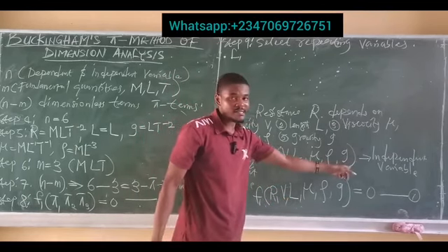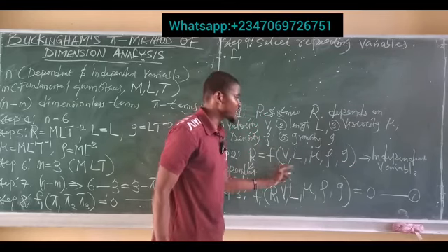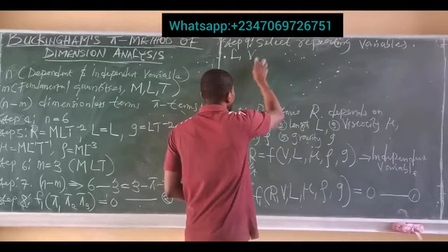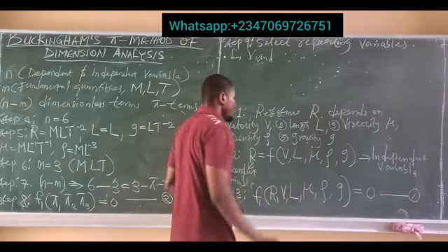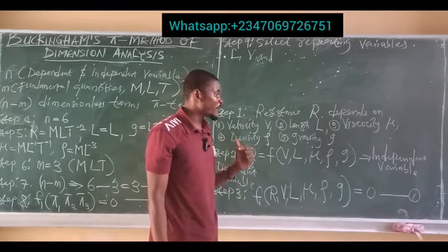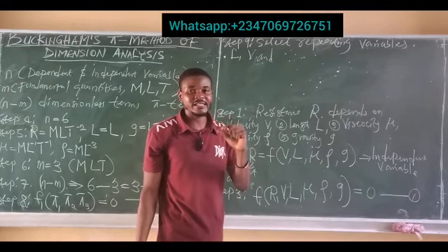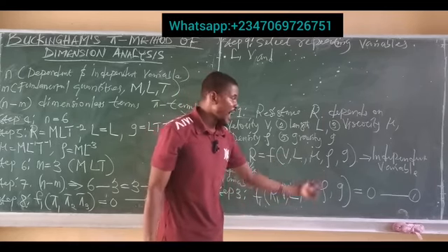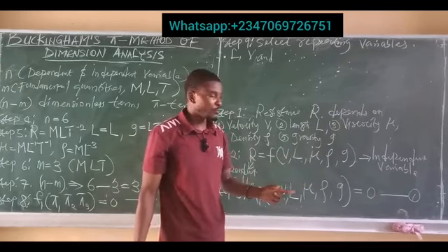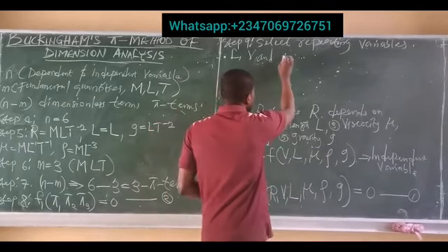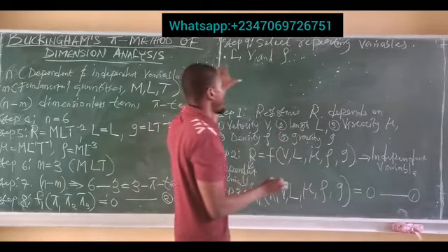These 2 are flow properties, but always prefer velocity ahead of gravity. So we choose V. And finally, the third property must be a fluid property. And I said amongst the fluid properties, always prefer density. I have dynamic viscosity here, it is a fluid property. I have density, it is also a fluid property, but always prefer density ahead of dynamic viscosity. So we simply pick density.